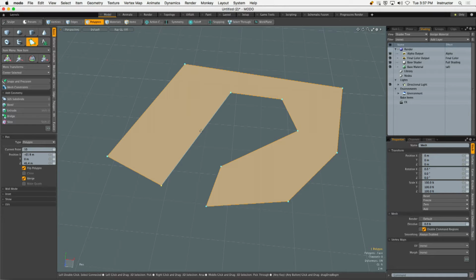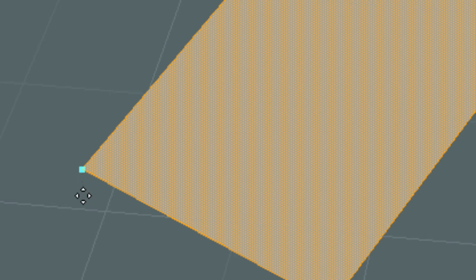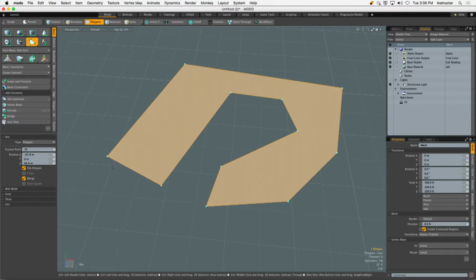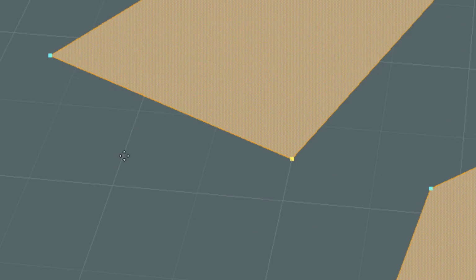Okay, I want to show you some UI here that is important. You're going to start to see this, and you have seen this in other areas of the Modo modeling tool set. Specifically, what I'm talking about are these little blue cubes. These little blue cubes down here are the control points for the pen tool. Now, these are editable. While the tool is still on, I can go in and grab that little cube, move it around, change the shape. Life is good. Notice that the one that I just grabbed is always going to be gold. There's always going to be a gold cube on your pen. That means the gold one is the active one or the current one.